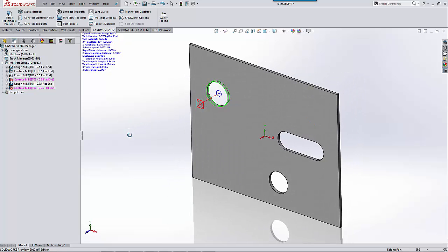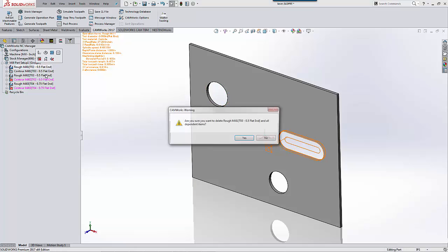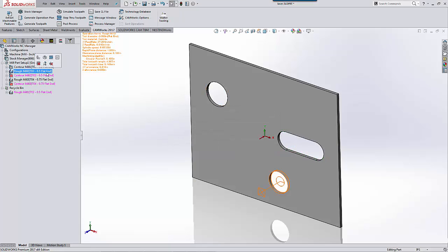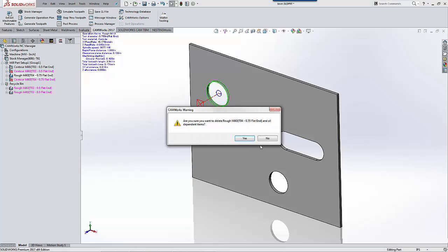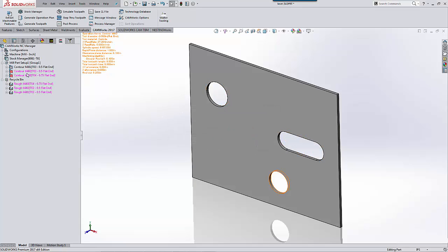Generally on a laser you're looking at 5 thousandths to 7.5 thousandths in diameter. The other thing is we only want to cut it once, and we want to use cutter comp. That way it offsets the beam thickness to the side. And so for those we actually use the contour mill. So the first thing I'm going to do is come through and delete the rough mills. All I'm concerned with is I want these finished contours.